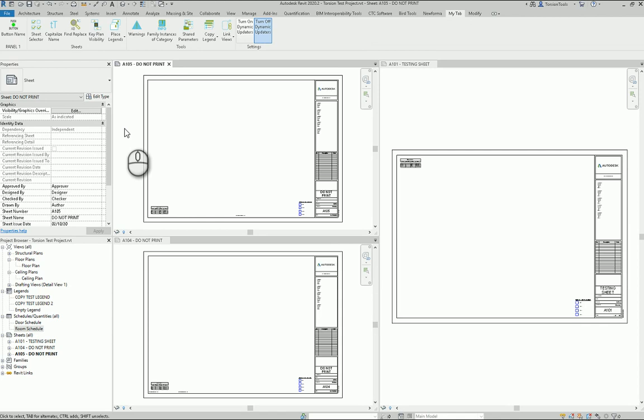So then the next piece that I want to look at is we added some ability to add shared parameters to multiple families at one time. This is, again, something I've had built for quite a while now. I've just seen the functionality of it more now. So this not only adds shared parameters to the families, but it'll also update the families to whatever the current version of Revit you happen to be using. So I'm in 2020 here. So if any of the families I were using were older than that, it'll automatically update them.